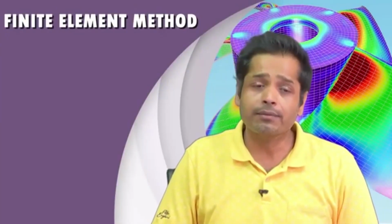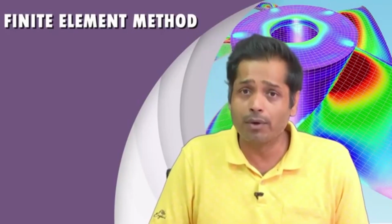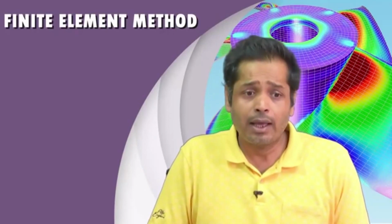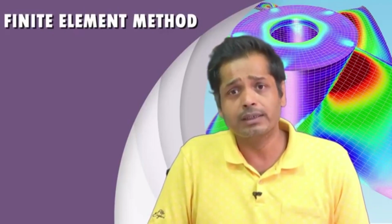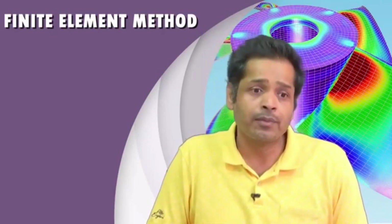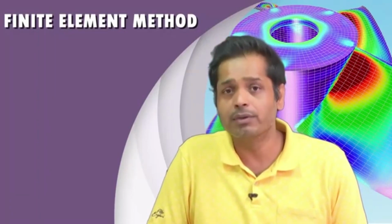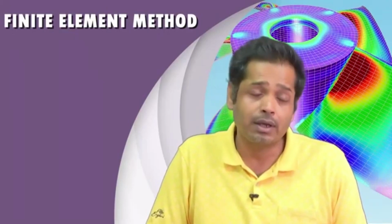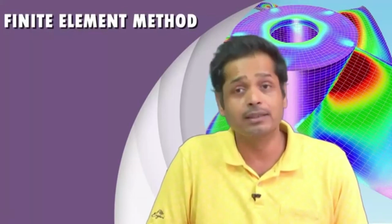And what we did there while constructing the shape function, we first started with a polynomial approximation, and in that approximation we have certain constants. Then we impose a condition that the approximation should interpolate the nodal values, interpolate the primary variable at the nodes. With this condition, we determine those constants, and eventually we have the shape function. Because of this imposition of this constraint, the final shape function has the interpolation property.